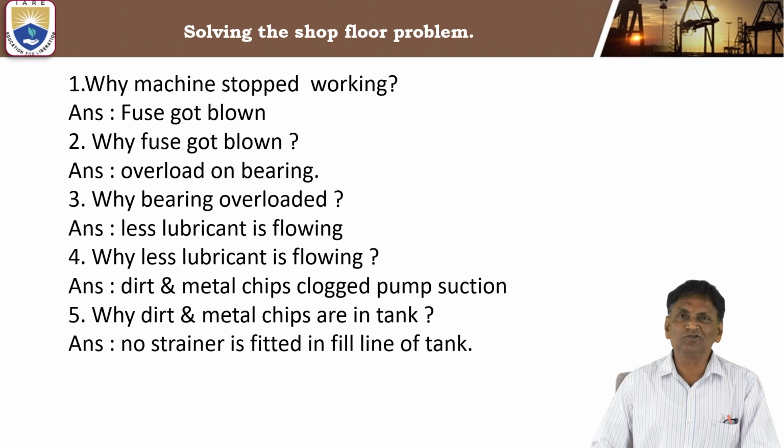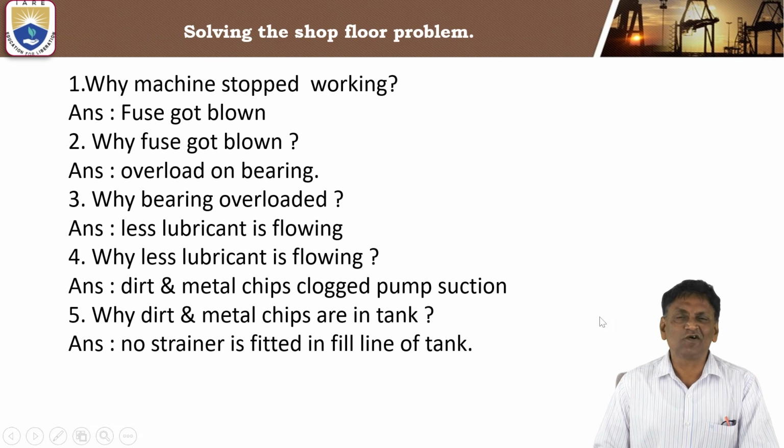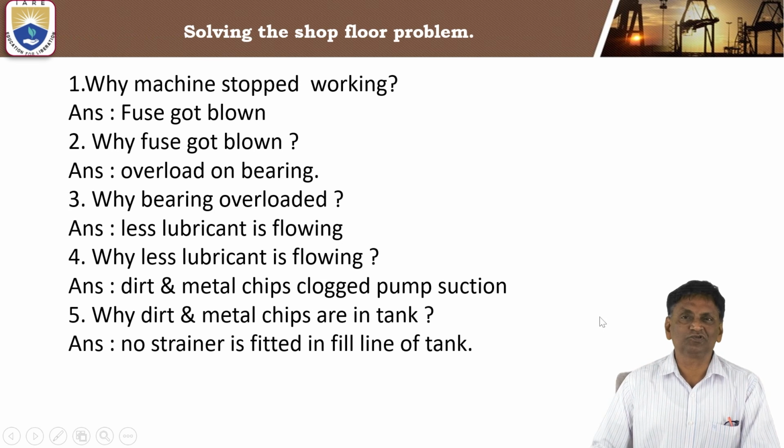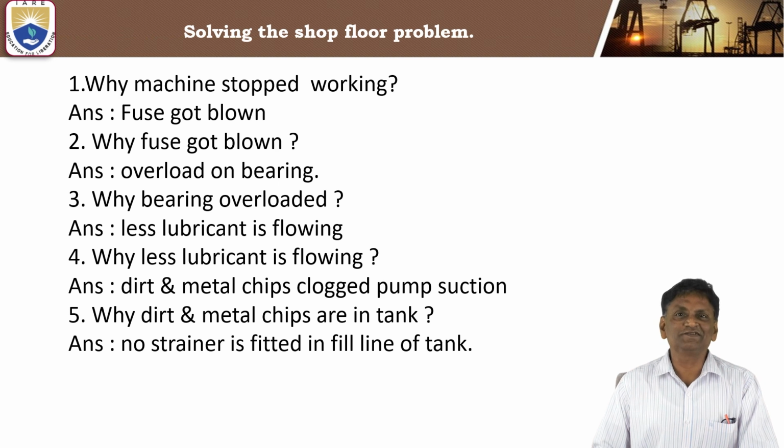If you put those things in logical order: why did the machine stop working? The fuse got blown. Why did the fuse get blown? It is an overload because the bearing is not smooth. Then why is the bearing overloaded? It is getting less lubricant and some particles also.